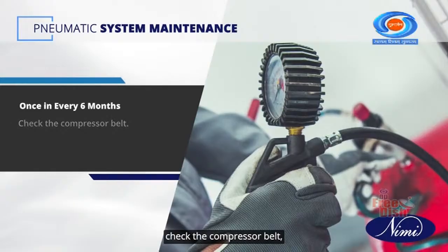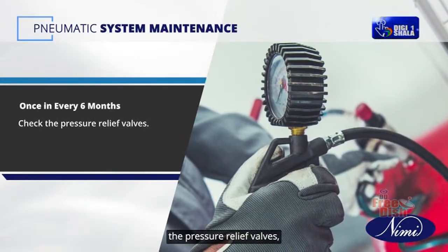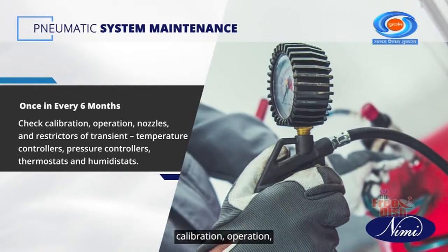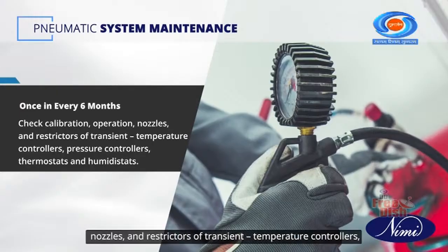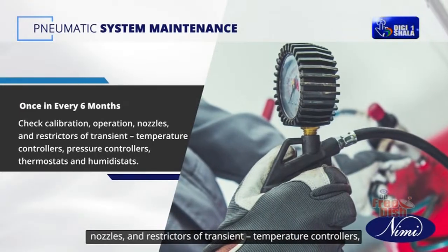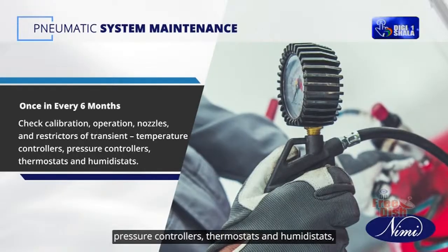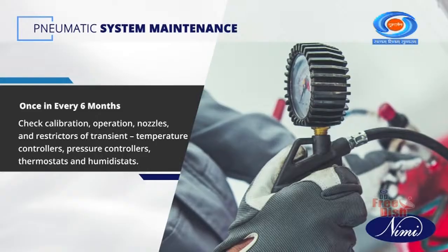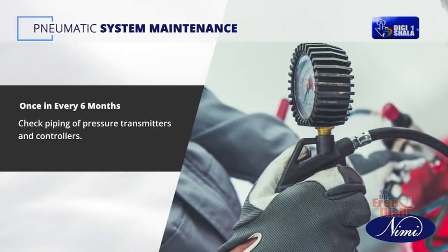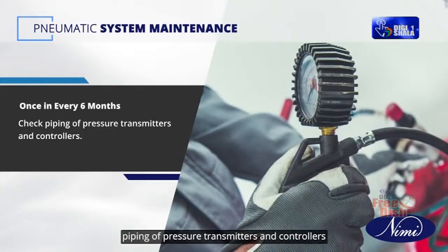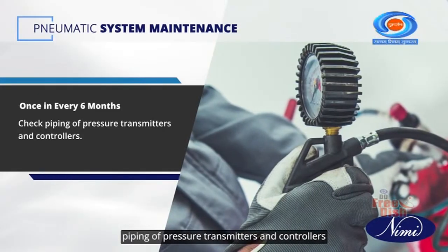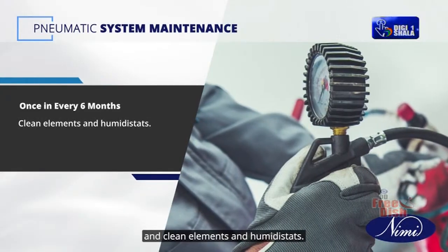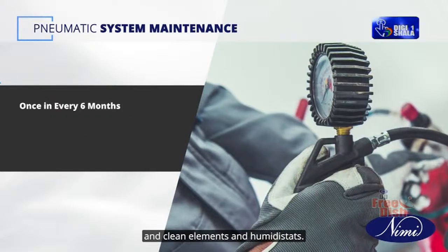Check the compressor belt, the pressure relief valves, calibration, operation, nozzles and restrictors of transient temperature controllers, pressure controllers, thermostats and humidistats, piping of pressure transmitters and controllers, and clean elements and humidistats.